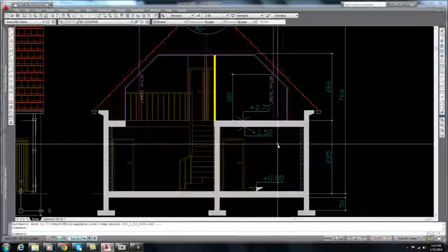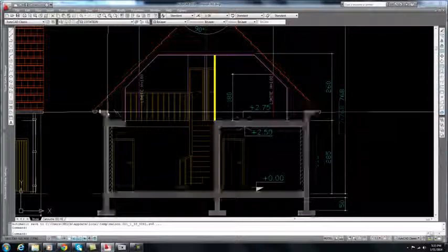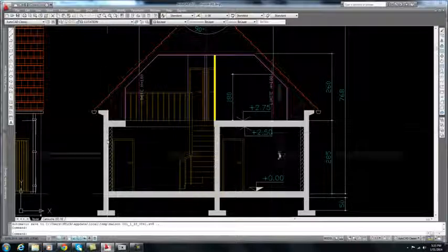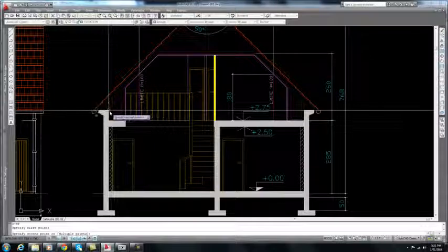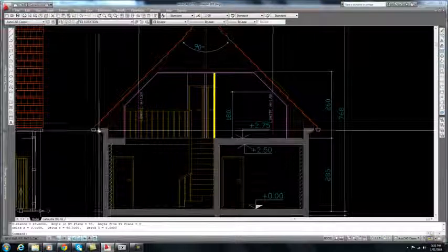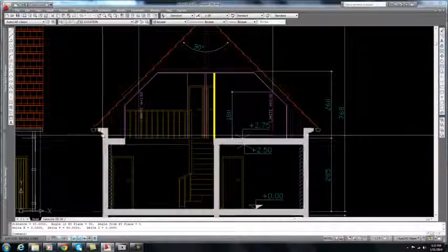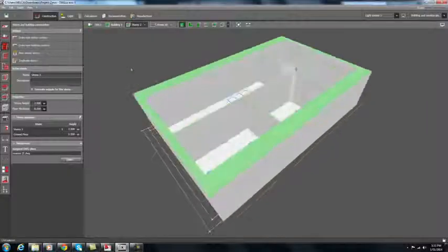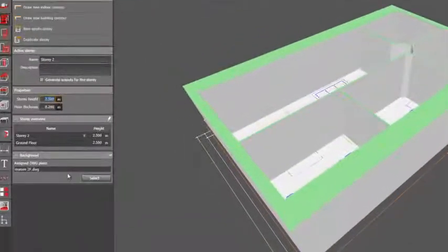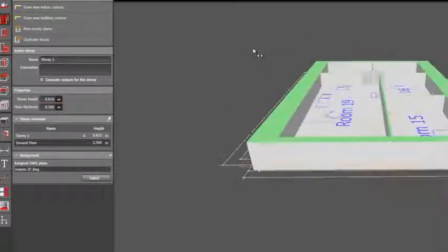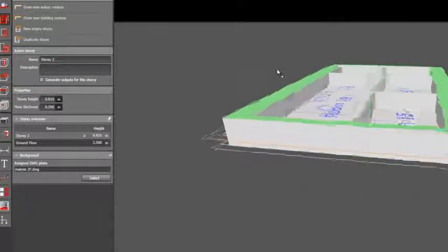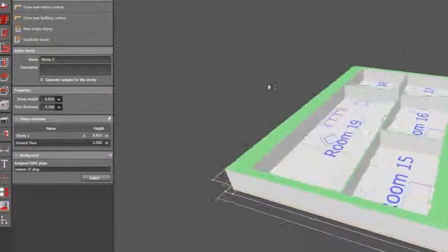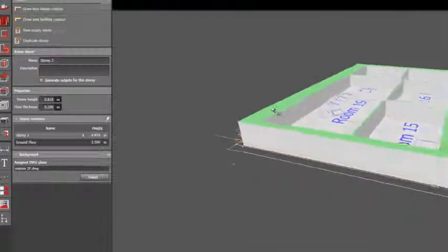But if you see in the CAD file, the wall in the second floor is too little. Unlike on the ground floor, it's like 2.5 meters high. But this one is like, let's check, it's like 40 centi. So we will create a 40 centimeter wall first. Go back to this file, and you can see here the default is 2.5, so we need to make it 0.4, or 4 centi, and then enter. Then it will become like this. Why I do that? Because I need to create a roof. There's maybe another technique, but that's how I did it. So I will show you how I did it.